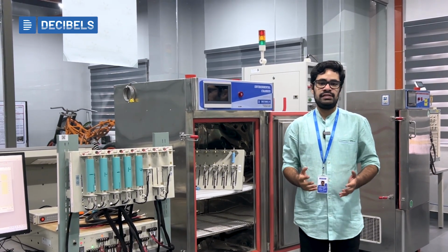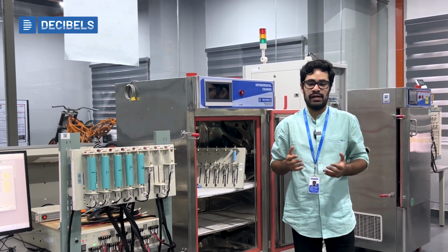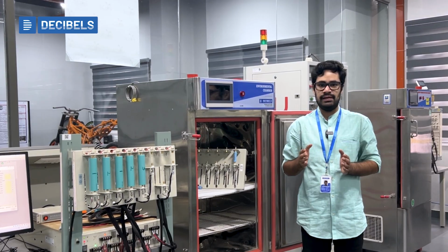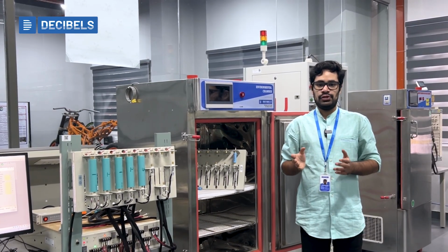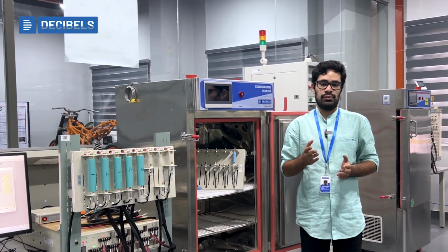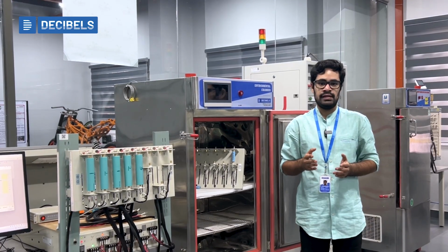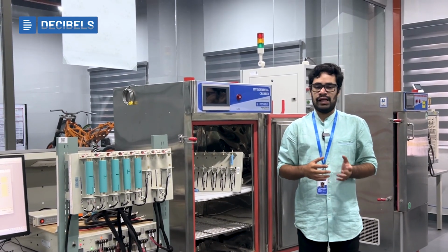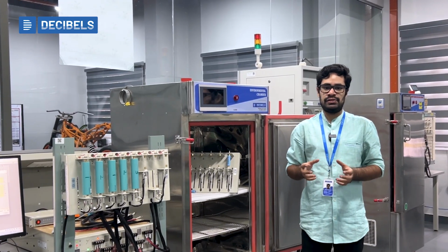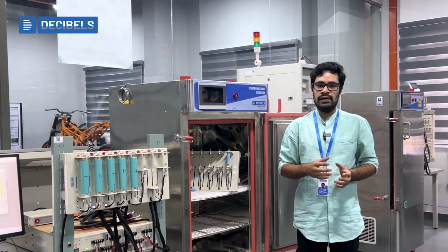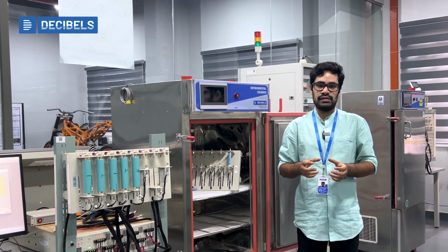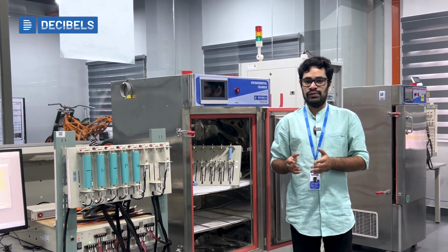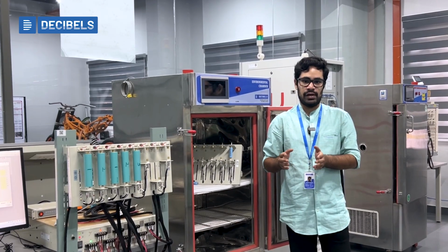The two types of characterization tests conducted are a static capacity discharge test, which gives information on how the cell's discharge capacity varies with ambient temperature. Naturally, at 0 degrees Celsius it's totally different from 25 degrees Celsius, which is different from 45 degrees Celsius. Along with this, another test called Pulse Power Characterization or HPPC is performed to determine the cell's internal resistance. This too will change with respect to temperature. Further on, we will see how the graphs vary with temperature.